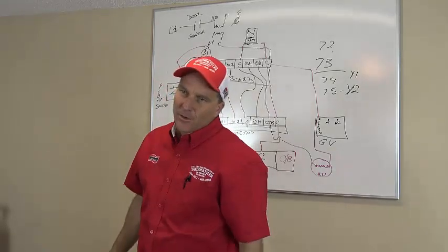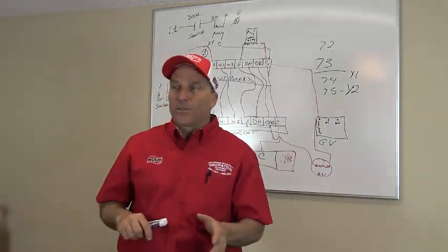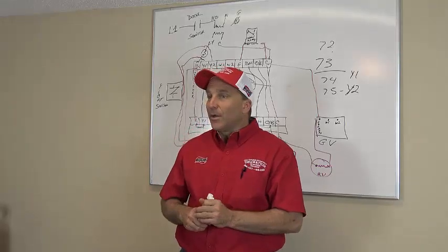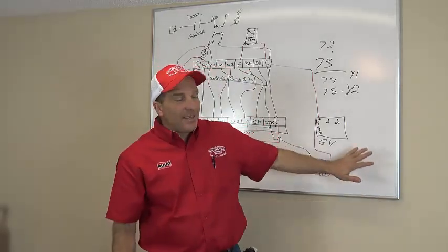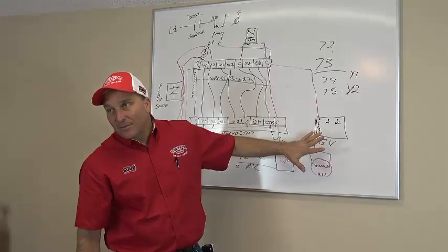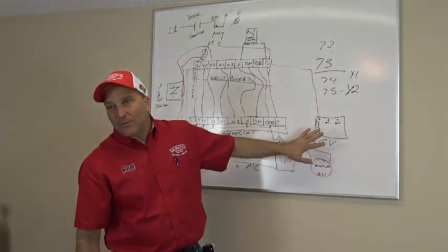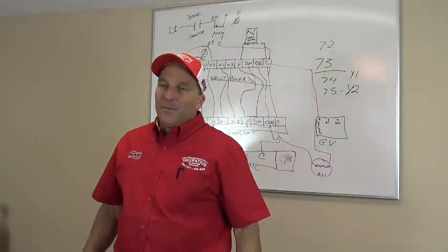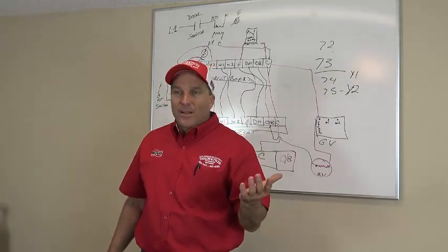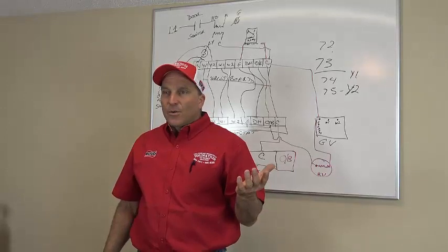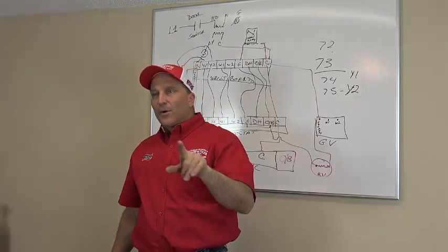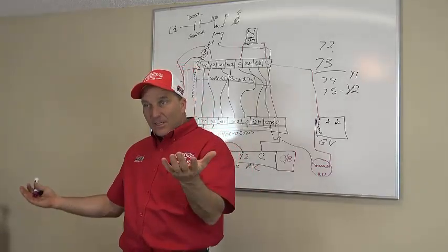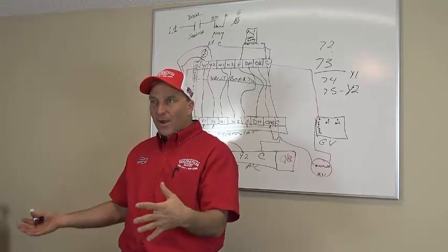There's a defrost sensor on the outdoor unit on some units, not all units. What does the defrost sensor do, guys? Think about it. How does it do it? It de-energizes the reversing valve, right? And when it de-energizes the reversing valve, it also sends a signal and turns your fan off on the inside. So there's no fan motor running on the inside, okay? So now what happens is it reverses the refrigerant back around, and when it does, it puts the heat outside and defrosts it. Defrost sensor, right? Freezes up, defrost it, right?